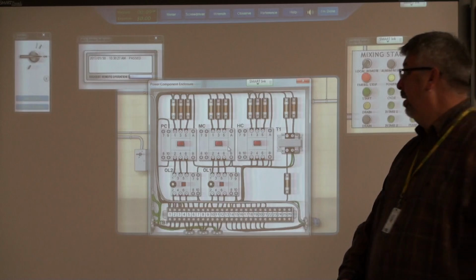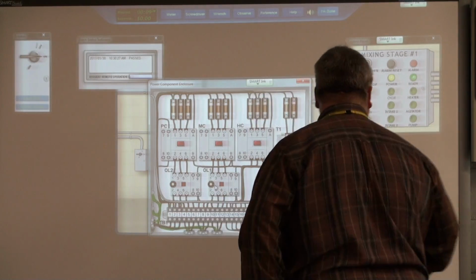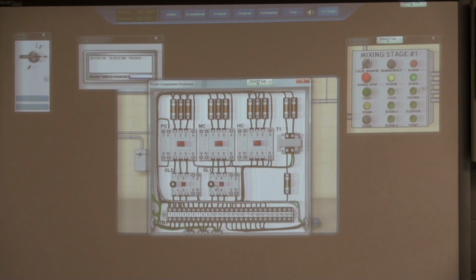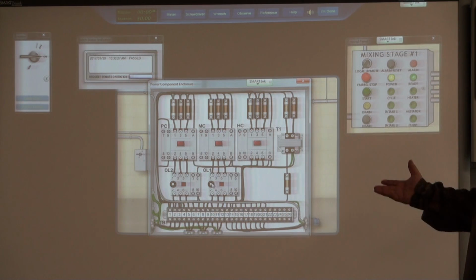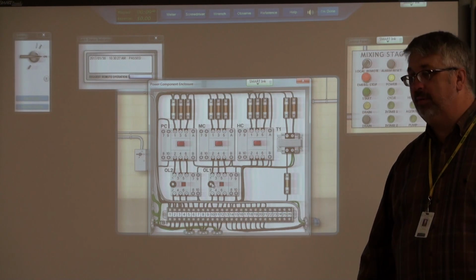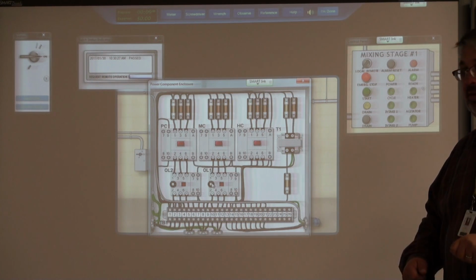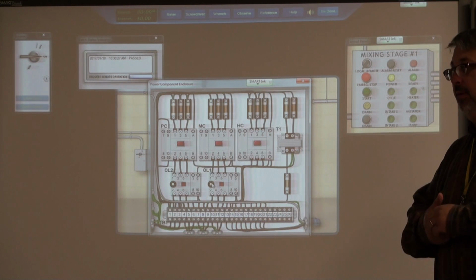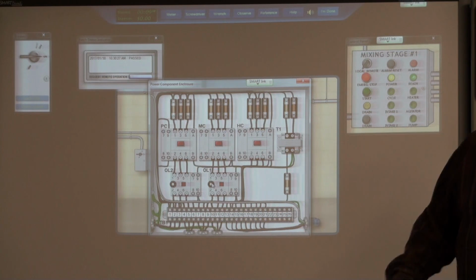What's the little black dials on the overloads? Those are actually settings. I don't think you can mess with those on here. It's the time that you can set. Yeah, or you can zoom in. In other words, if it pulls 5 amps for 1 second versus 5 seconds, how quick do you want to trip that overload, basically? So it's a delay. If there is a sudden spike, if you're feeding a saw and it jams for half a second, you don't want to just trip the relay, but if it jams for a second or two, then it might be time to cut it off.